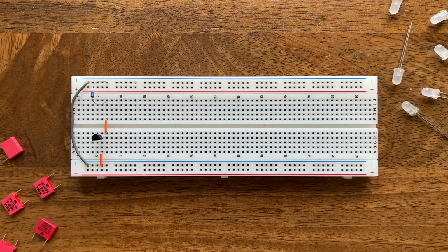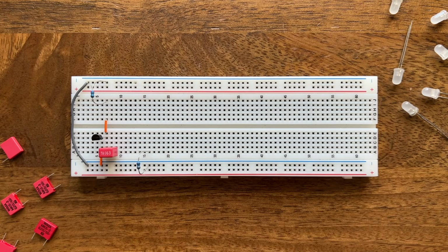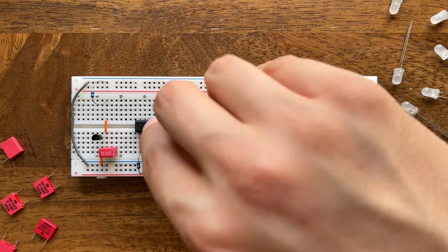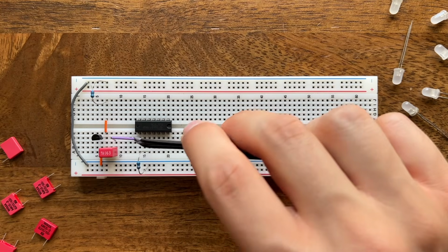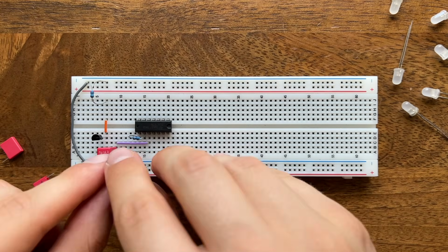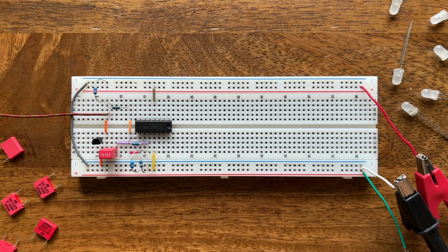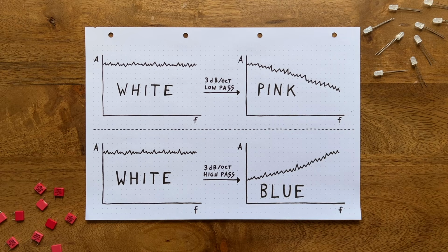To test this, I'll first connect our transistor's emitter to a 1 microfarad capacitor, followed by a 100K resistor to ground. Then I'll set up a TL074 quad op-amp chip. Next, route the other side of our capacitor to one op-amp's non-inverting input, while setting its gain with the 100K 680 ohms voltage divider. Add in the output socket and we're ready to give this a spin. That sounds sufficiently noisy to me. Okay, one noise color down, white.